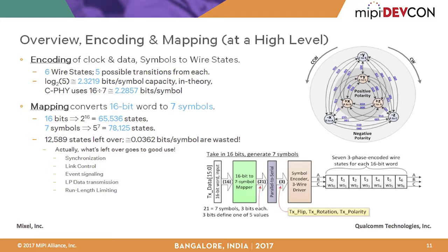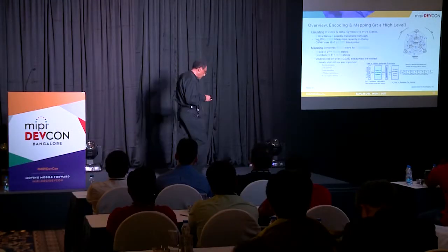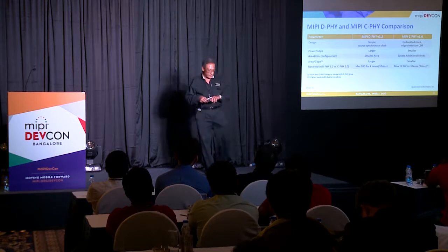One interesting feature of the C-PHY is that although it's a multi-amplitude system, on the receiver side, you are really not looking at the multi-amplitude information. You are only looking at zeros and ones again. I mean, it's a differential input. You are looking at the difference between the two. You are not trying to detect the difference between the high and the mid, for example. So that, of course, simplifies the receiver. Basically, you end up using the same kind of receiver that's used for the D-PHY.